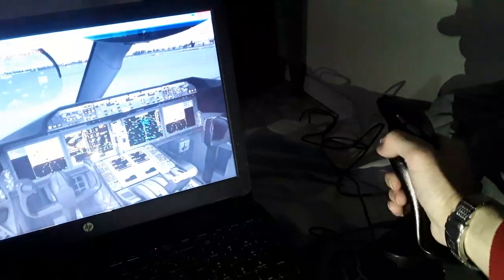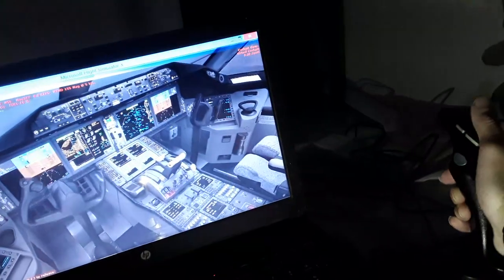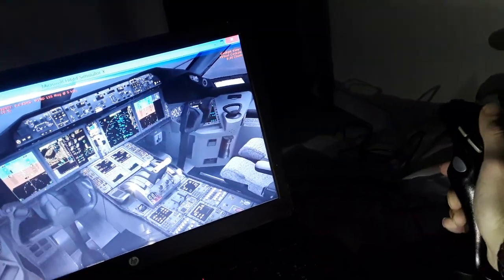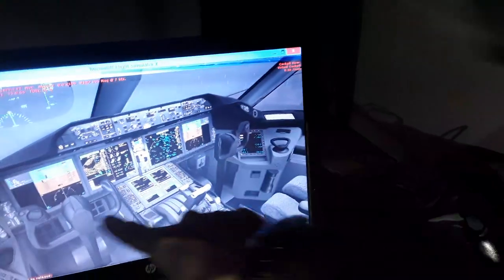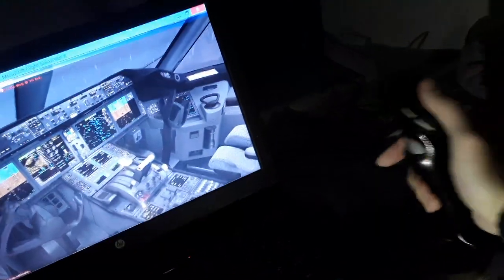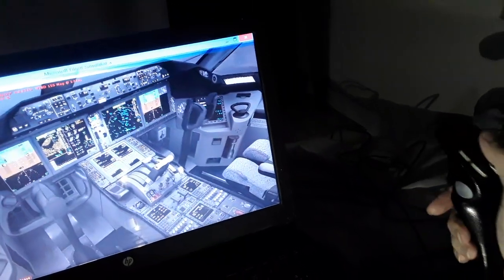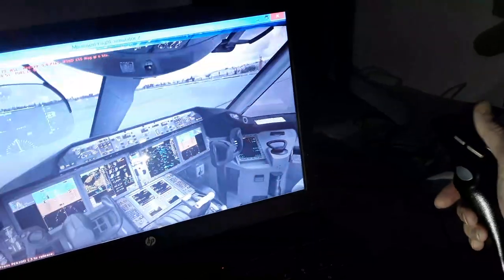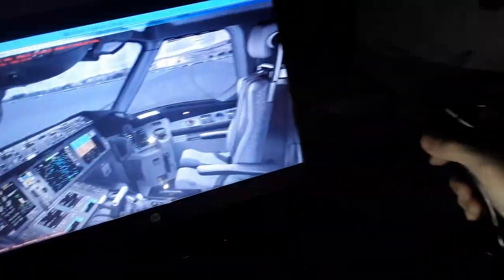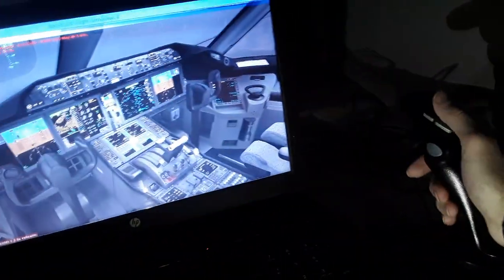You can see side stick deflection is proportional to the yoke and rudder pedals deflection and control wheel. Also you can see in the Boeing aircraft both the captain and the first officer are interconnected. Both sides move together simultaneously all the time unless you have a failure of the flight controls system, which will need to be overridden. You use override force from either left or right side. So in the Airbus you have the side stick priority. You can use either side stick instead.